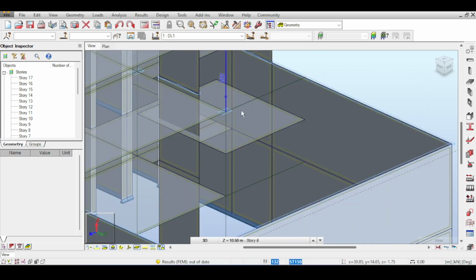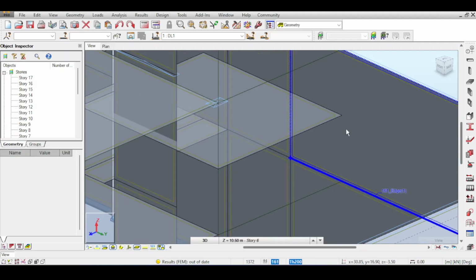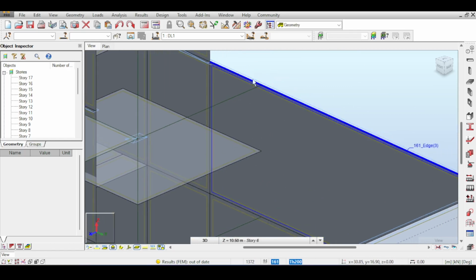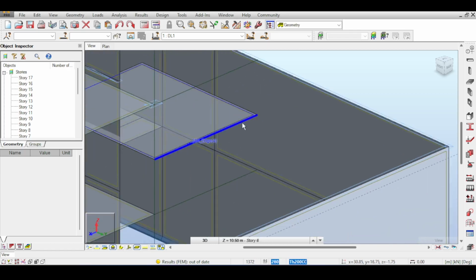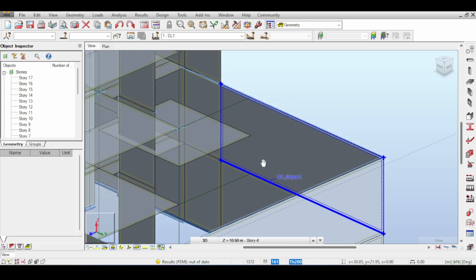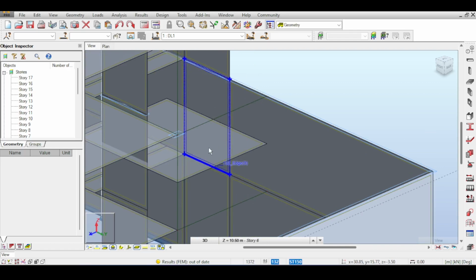This is the level of what I'm talking about here. So I will be needing a beam in the future. And this beam could rest on the basement wall, but it also needs a column here because, yes, I have a basement wall for the 2 ground or underground floors, but I don't have a basement wall for the top floors. So is it going to float in midair?